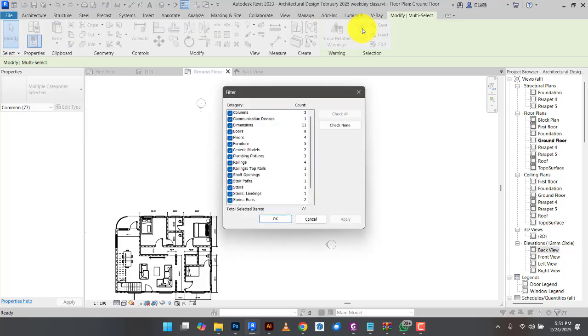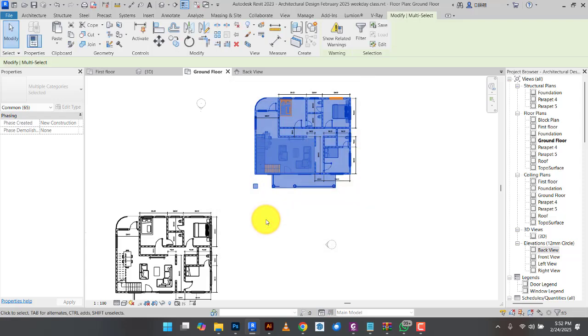then you look through. I'll remove the dimensions. So look for dimensions. Then you remove what we call the stair path. The stair path is that up. You see when you do the stair, that up, no matter, it's peculiar to that floor. So you cannot take it up. That one will need a new one. So you remove the stair path. Then click on OK. When you do this, you have to copy again because that first copy is still there.